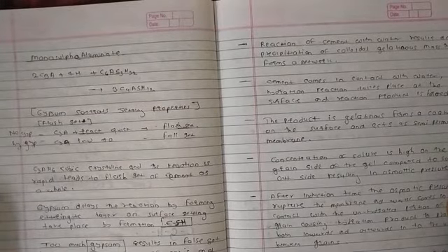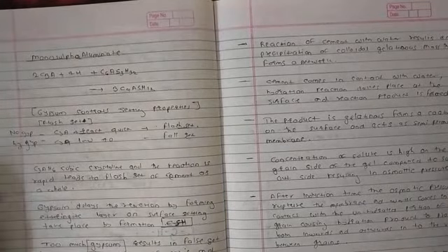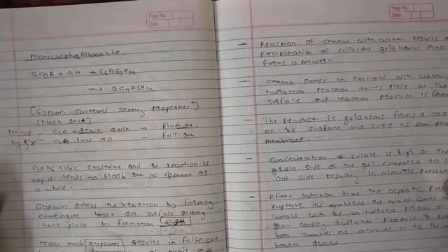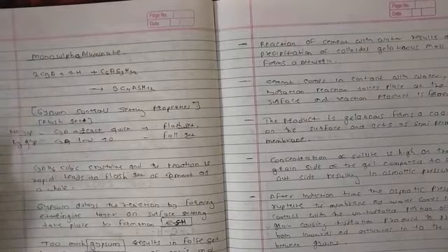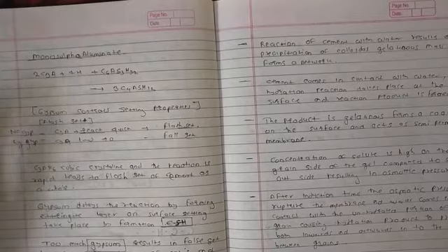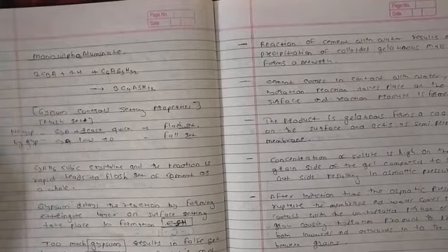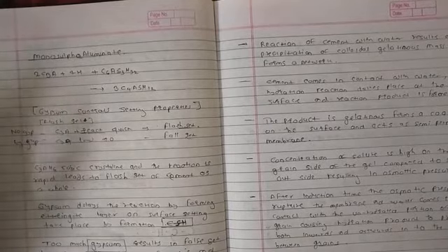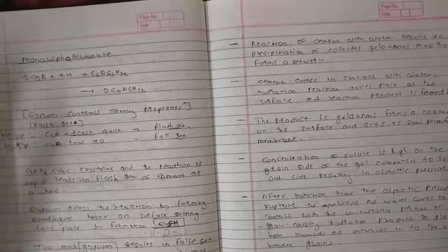These are the monosulfoaluminate. Very difficult to understand for newcomers, but after that you can understand. Why is gypsum added to cement? To avoid the quick setting of cement. We are going to look into it in detail after some time, but just to remember, gypsum is added in the cement manufacturing process to avoid the quick setting of ingredients. Majority for alumina, Al2O3.